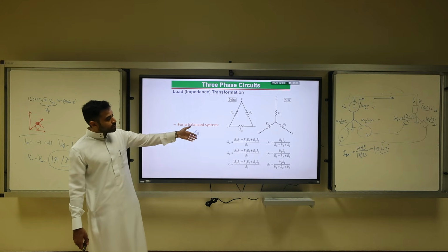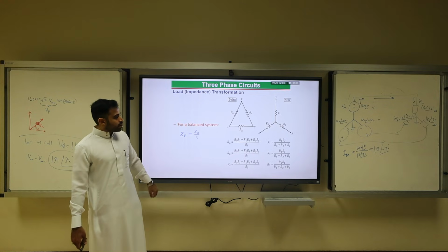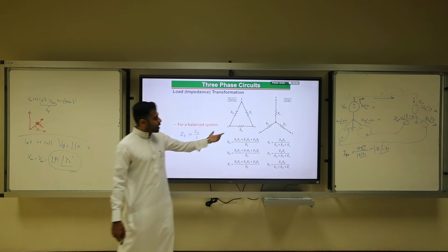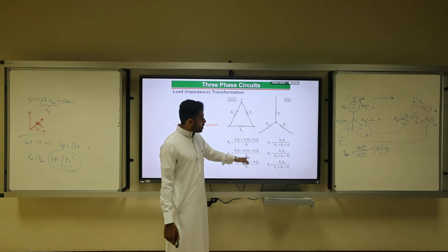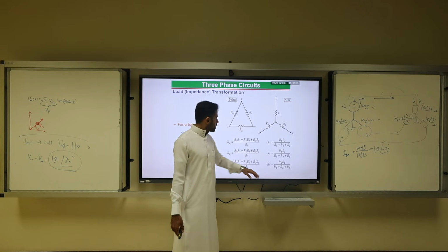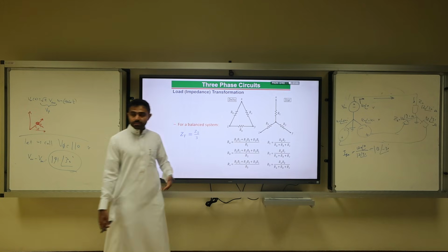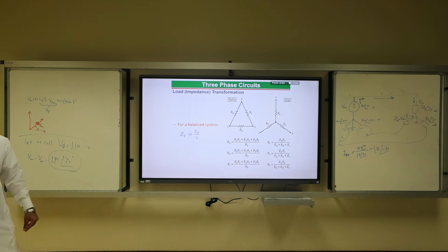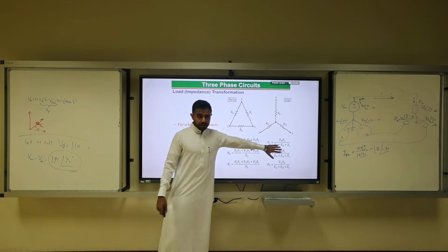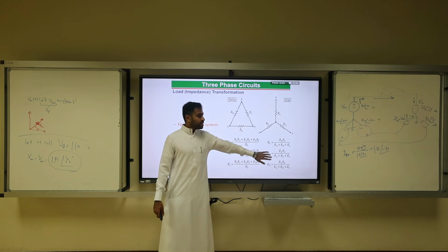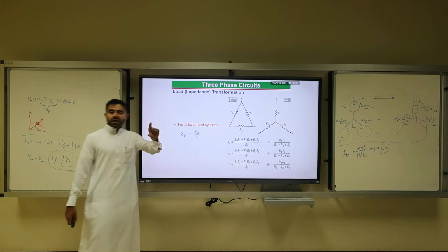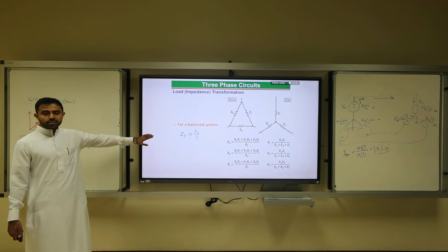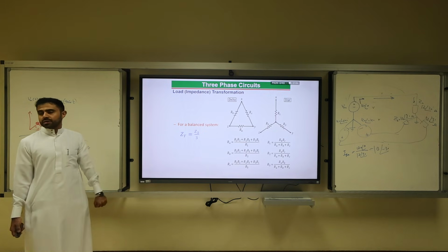And here is the derivation of this. As you can see, RA is actually (R1R2 plus R2R3 plus R3R1) over R1. Here you can write R1 as a function of these, and if you divide these numbers, you will end up with the number 3. Okay? Question? Well, don't worry about this. The better derivation is using power calculation. You have to prove that they have the same power, but no need to derive. Here we just need to convert delta to Y quickly. You got that?